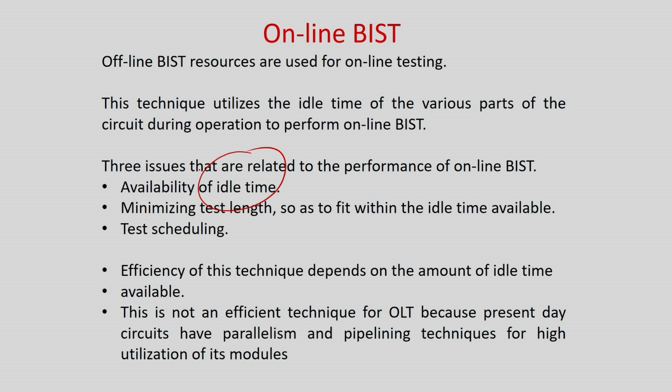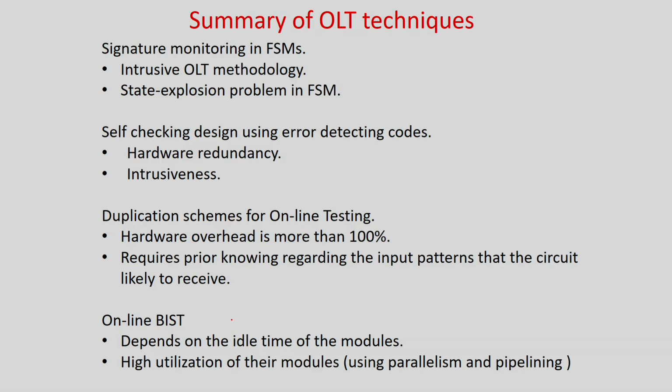And why is its popularity going down so much nowadays? Because nowadays parallelism and pipelining are in the picture. They always try to bring down the idle time of the circuits for high efficiency. So online BIST is not a very popular technique nowadays for most applications. Generally, if you have designed a very peculiar circuit where there will be a lot of idle times, then they can apply this. So as of now, this is the summary of the online testing schemes.